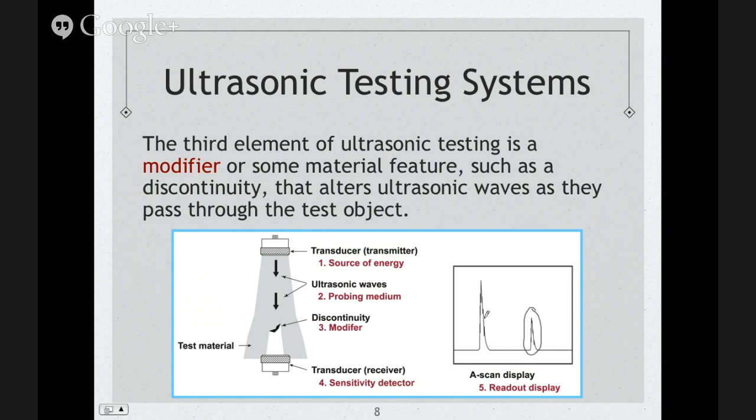Because you're losing sound, if you have a loss in sound, your indication amplitude tends to go down. The procedure will tell you that if you calibrated this at no discontinuity to be at 100%, let's say, and your amplitude goes anything below 40%, you discard the part or consider that a problem. So you do your inspection.